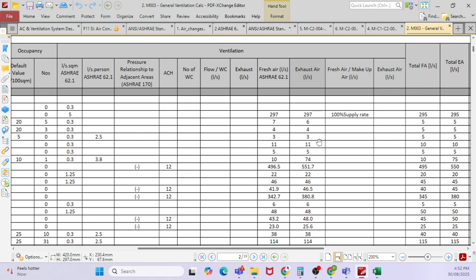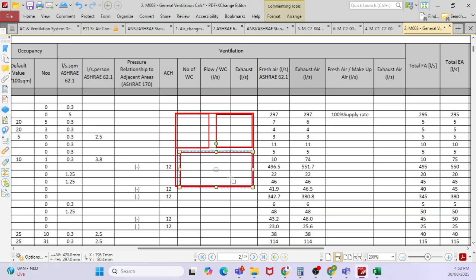Okay, so that will create either... if you want to provide one room, and I have a toilet here and a pantry here and a room here, for example, a hall. So I am providing fresh air here. Whatever fresh air goes through this particular space and through this particular space, I can make it neutral. In case I have one common room, in this particular room I have to create positive pressure.